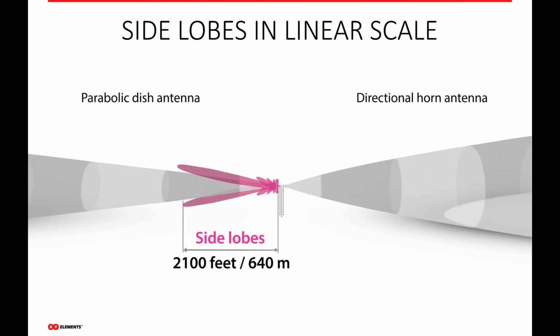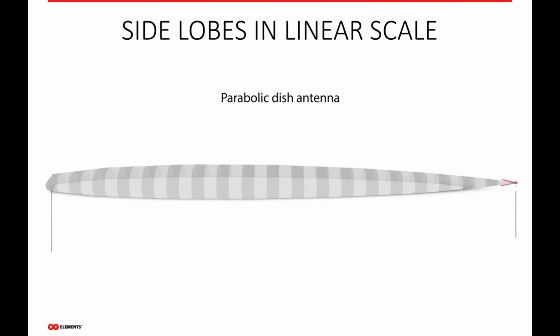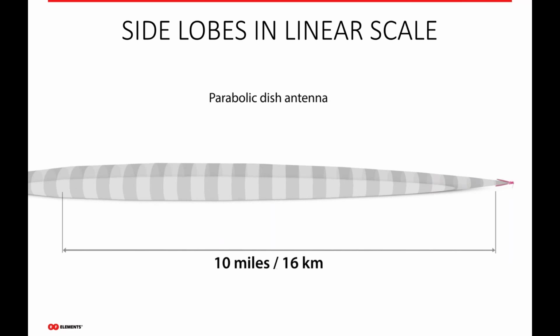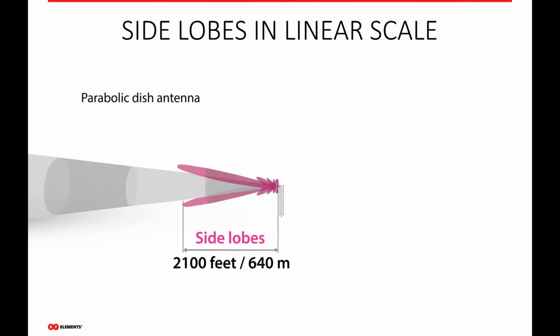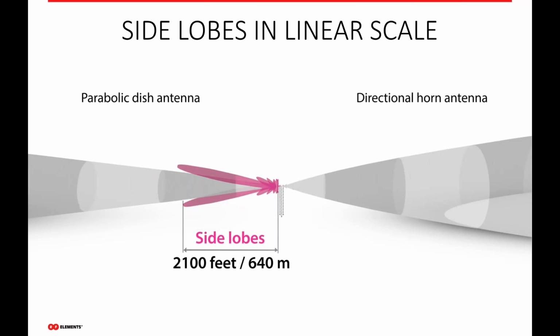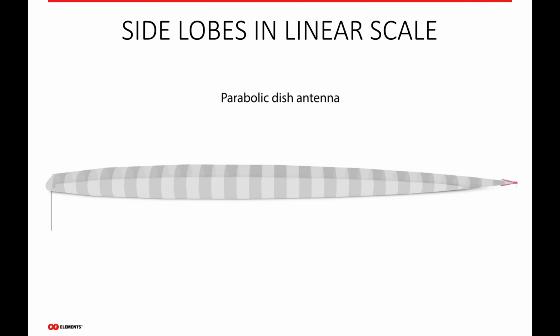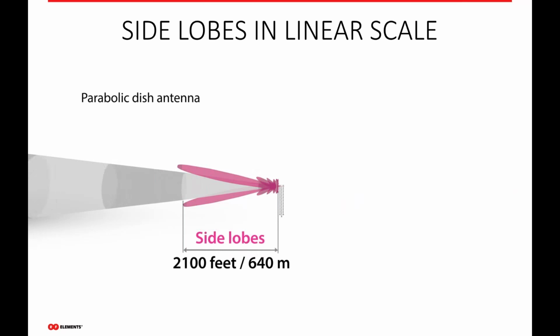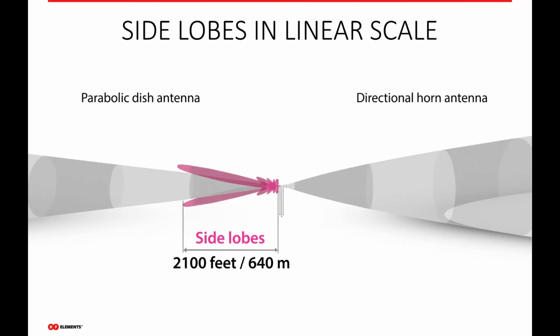Look at the horn antenna to the right. You can see that the directional pattern with no side lobes is much cleaner, and there's less interference to be sent or received. So again, it's very easy to have another competing tower 2 kilometers away from you, or even your own, like in this micro POP world where things are getting even smaller, even closer. It's very possible that your backhauls are causing issues because of their side lobes, even though we mainly focus on that main beam gain and main beam angle, right? The side lobes are something you seriously have to consider and do something about.